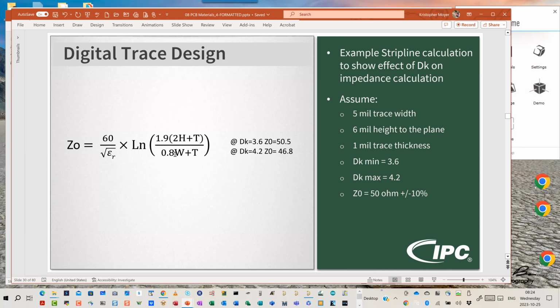And so they're basically saying, we're going to these narrower and narrower traces. We just can't hold the tolerance on that because of our etching process and the variance in etching, where if you could run your DDR using 5 or even 10 mil wide traces, yeah, they could still easily hold the 50 ohm or 40 ohm at the 10% tolerance. And my suspicion is that the DDR is pushing you to use the BGAs or even the micro BGAs where you're sub 1 millimeter pitch for the memory chips themselves. Am I correct in my assumption?